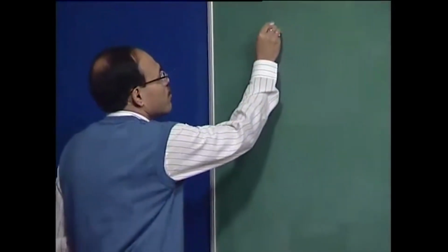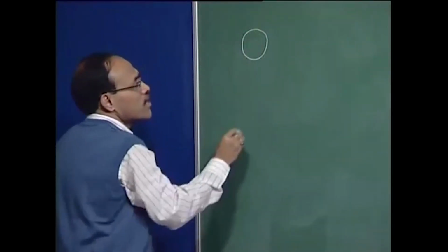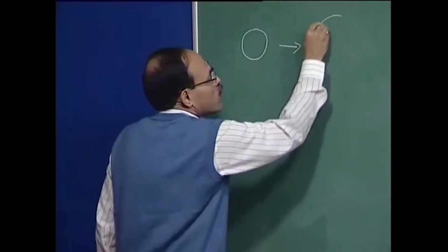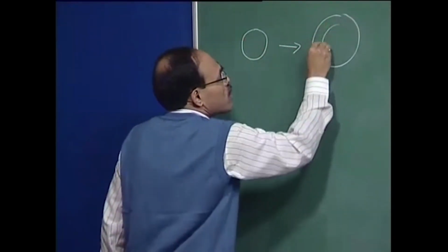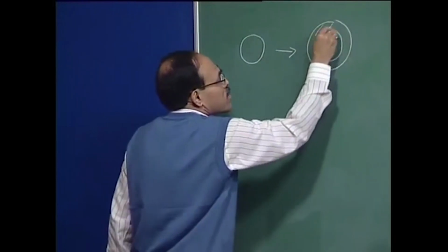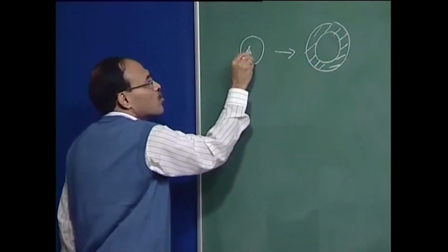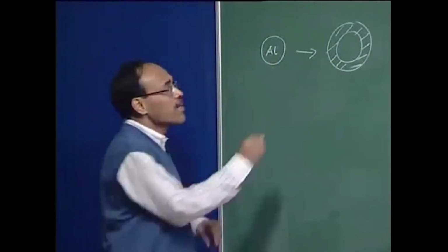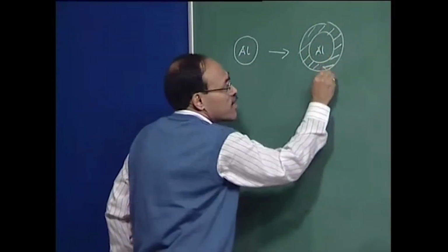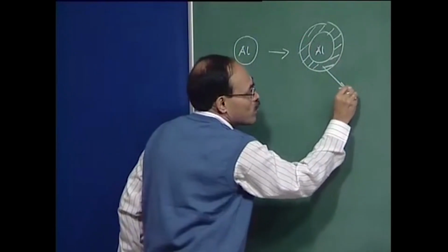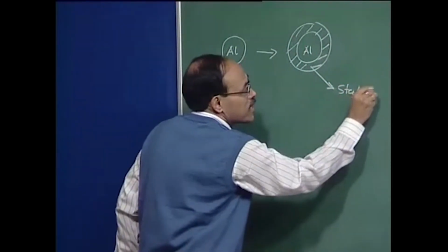So the solid, initially at room temperature, as it is projected into a liquid bath, typically what happens is that we have a solid shell which forms around the initial solid. So this is the crust. If this is aluminum, we can expect that the crust material is essentially the bath material, so this is going to be a steel crust.